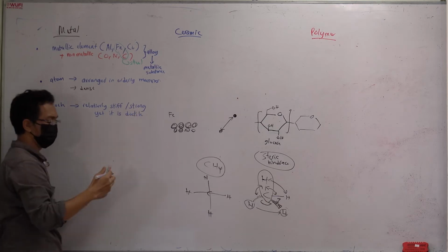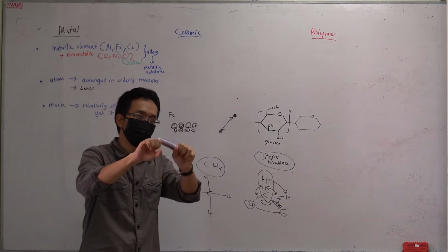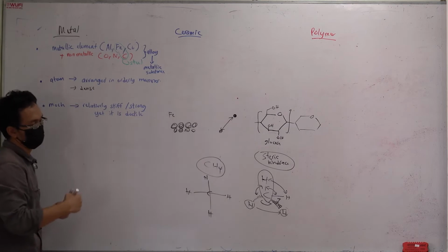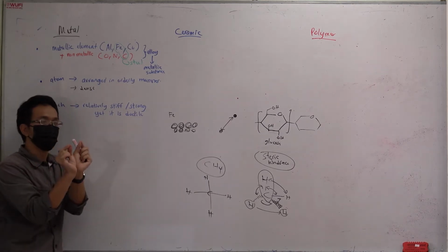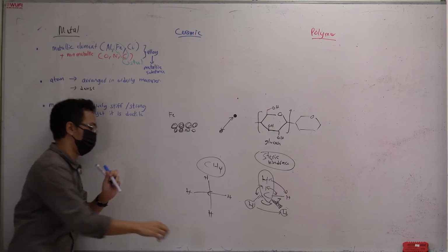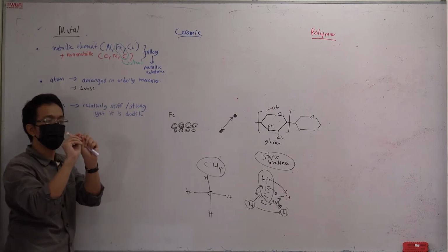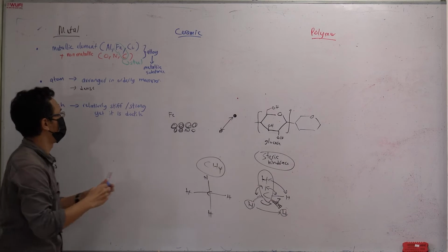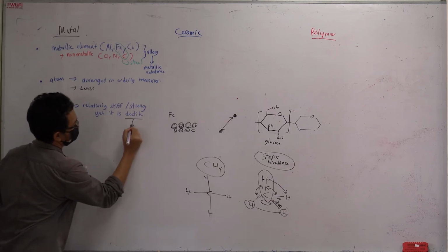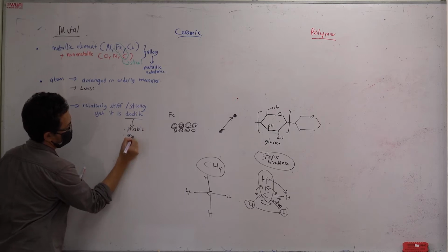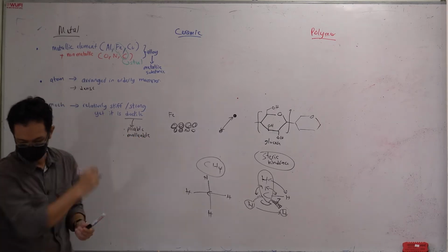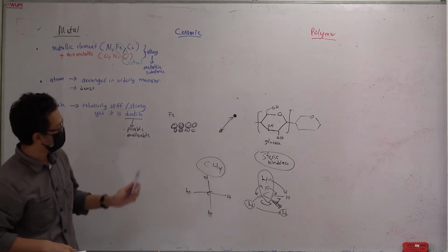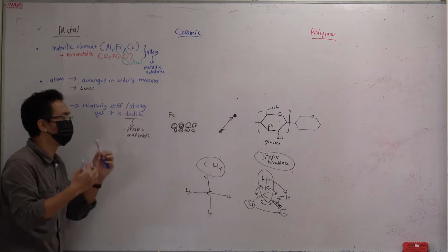Ductile means that it can sustain a deformation, a change in strain, without fracture. You have a paper clip, you can bend it without the paper clip snapping. If you have this polymer, if you bend it, it snaps. So that's what ductile means. Ductile means that you can make it pliable, or in other words malleable, whatever. Okay. So it's resistant to fracture. Ductile means it's resistant to fracture, snapping.